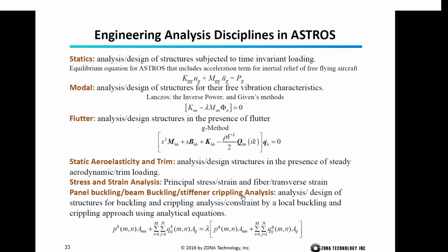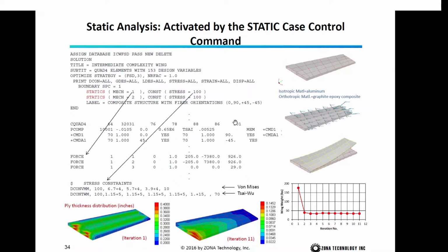We use the analytical solution, and we solve panel by panel to evaluate the panel buckling constraints. The static analysis is activated by the STATICS case control command. So you can specify STATICS, and MPC equal to 1. It refers to a set of force and moment cards. And meanwhile, you can impose